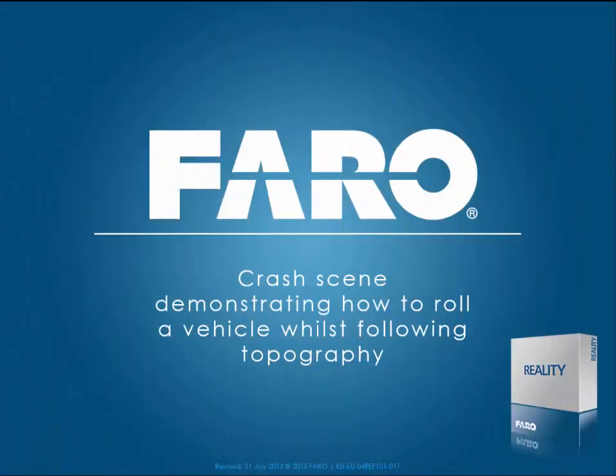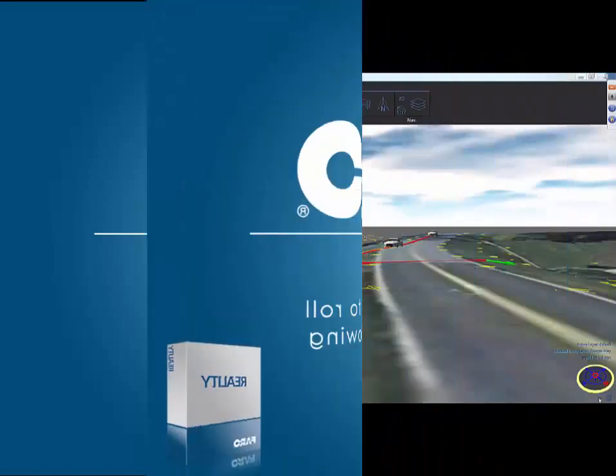Taking that one step further, we've downloaded a Google Earth image, which is fully scaled within the system, and then we apply once again total station data taken at the crash site to create topographical information from the Google Earth information. We then simulate the crash, and as you can see, the vehicle follows the terrain.